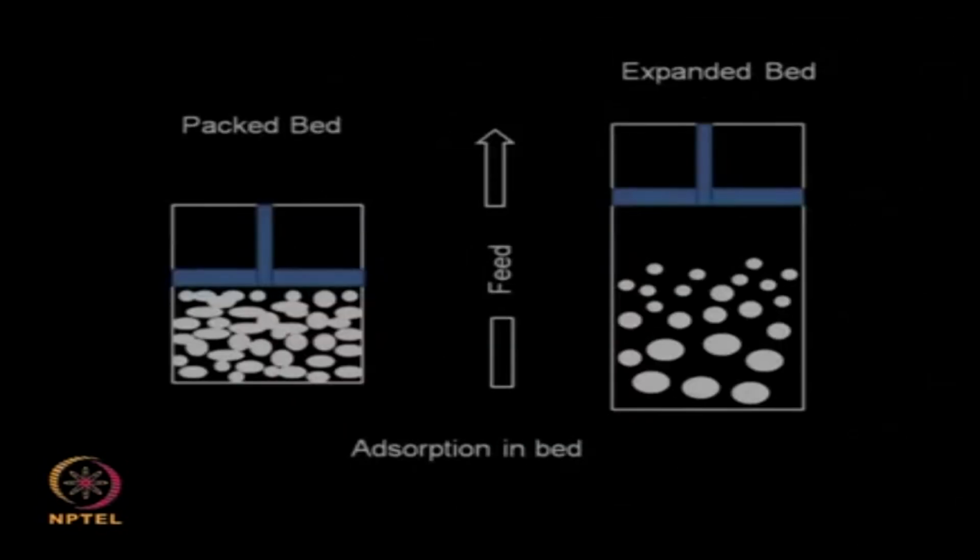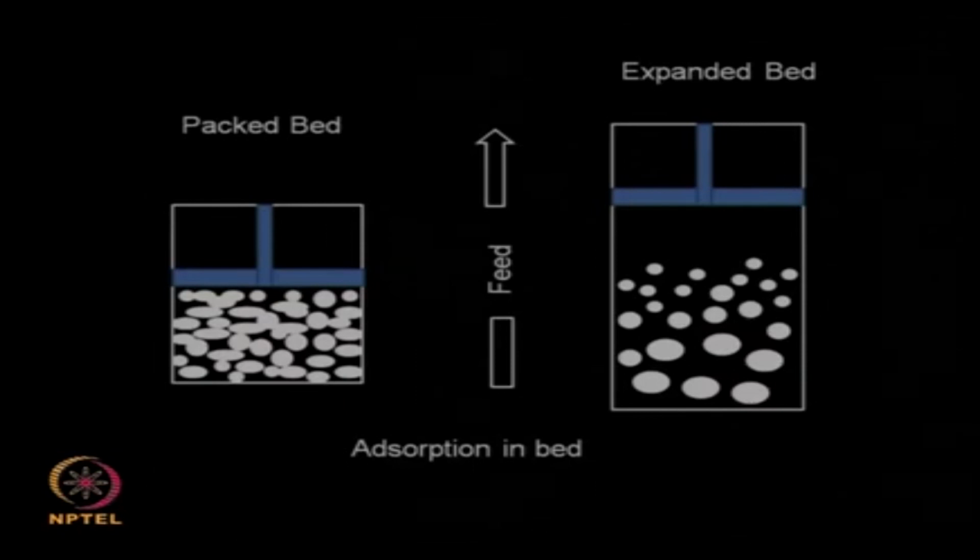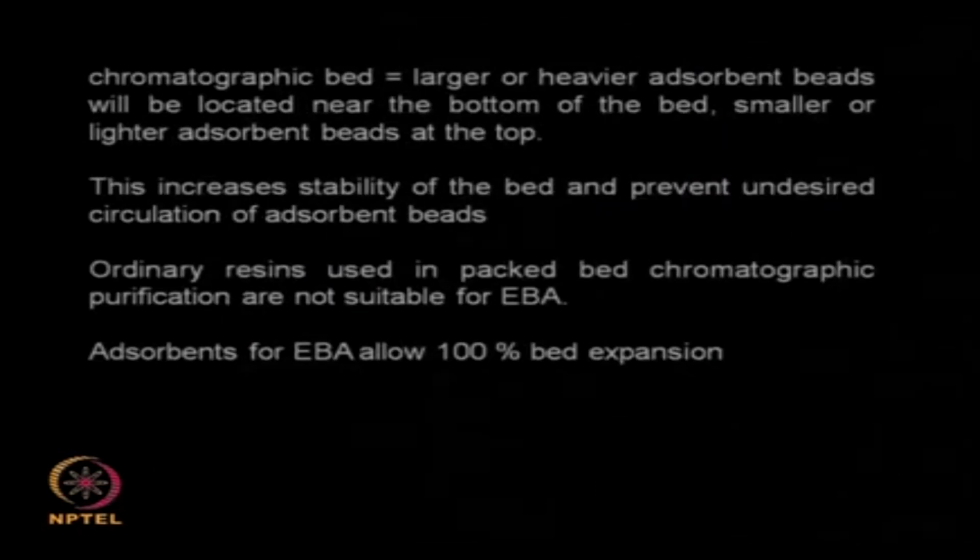Okay. There is another concept which is called the expanded bed. Just like a packed bed, you can also have an expanded bed. The expanded bed is almost intermediate to a fluidized bed, whereas in a fluidized bed the entire solid material is in a very turbulent and fluid state, in a packed bed the solid adsorbent is totally packed and there is no motion. So, basically you achieve the expanded bed by modifying the flow rate. The bed gets slowly expanded, so that mixing is better and the adsorption taking place is also more efficient. So, there is now more interest in this particular approach, called the expanded bed.